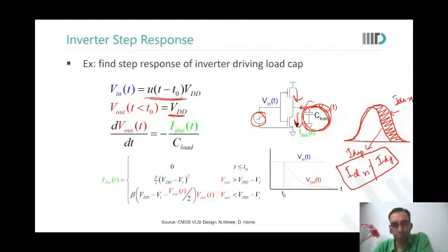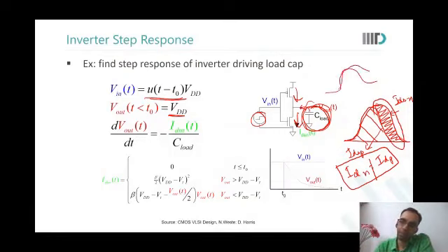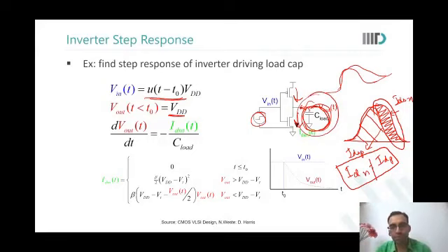Yes, sir. So the power will definitely increase. This area will definitely increase. Because this region is charge given by the PMOS. NMOS took all that charge. This was the extra charge. So this extra charge represents the charge coming from the capacitor. So if you are just given the current characteristics, you can find out the capacitance that is connected on the load. Are you able to see this?